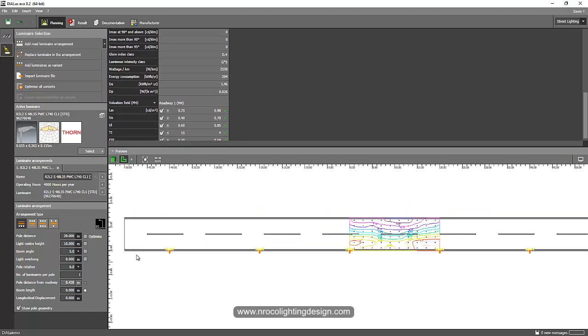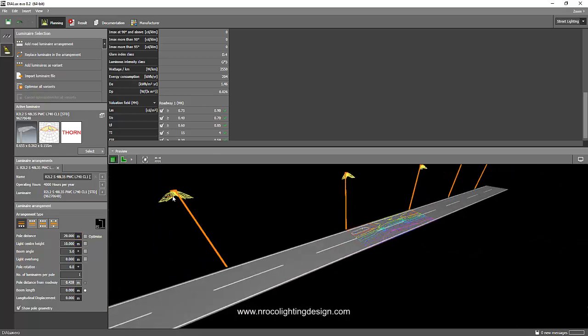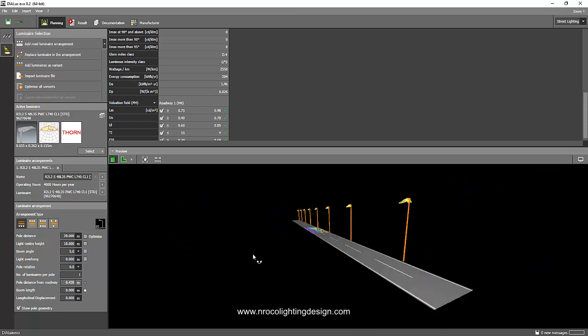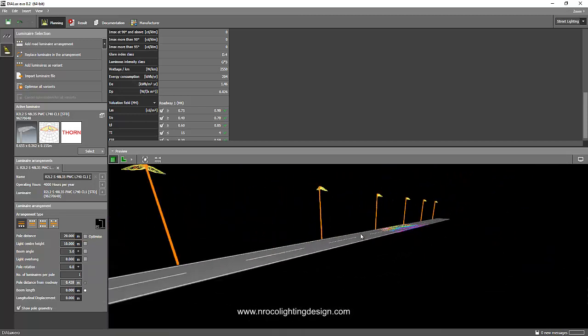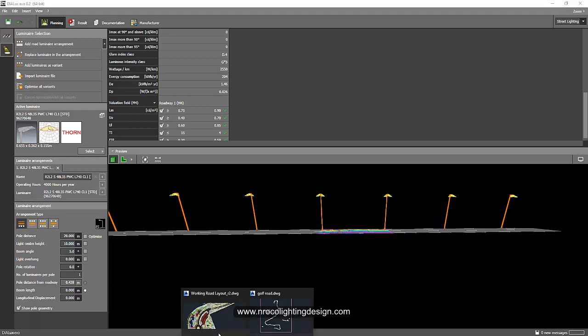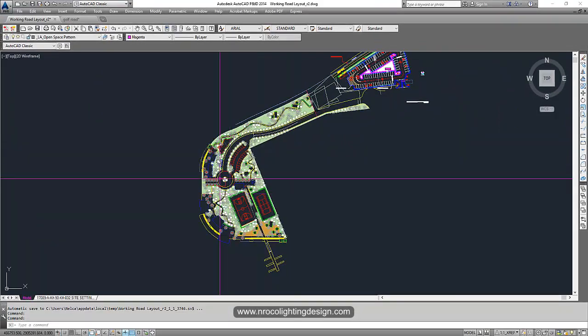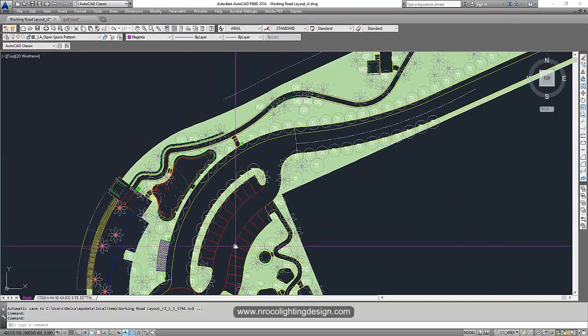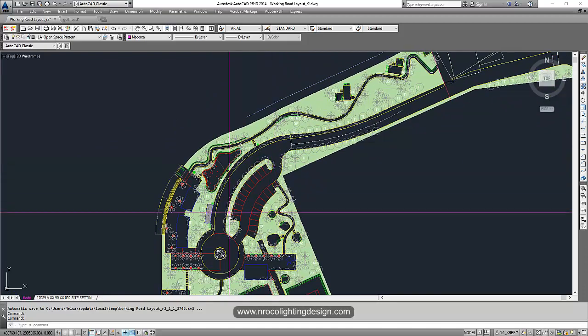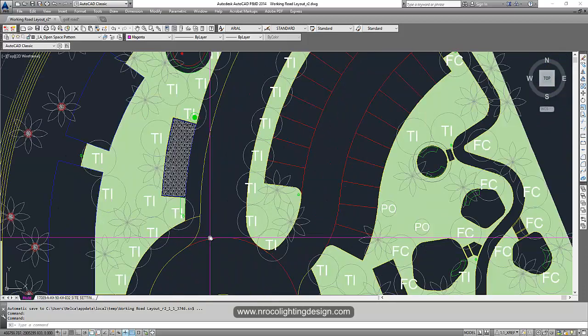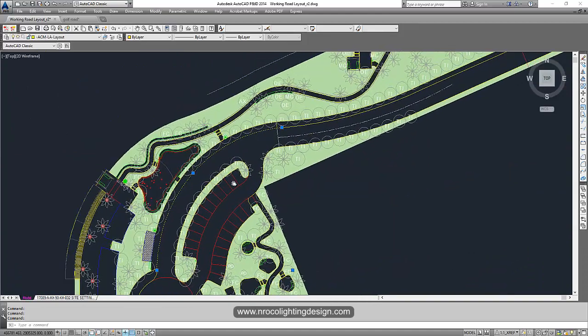So what you should do, because here I said 20 meters, now it's complied, is lay out this 20 meter spacing on your AutoCAD file. You don't need to run a calculation for a very long 1 kilometer. Okay, for example, I will show you how. Say for example this one, you can see that I have a small road here with a little roundabout there. Let's say for example I mentioned that the fitting is 20-meter spacing and this one is curved.